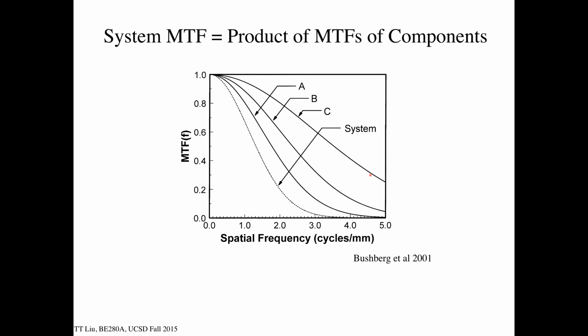Let's think about it a second. This system out here, system C, still has some amplitude for these high frequencies, right? And therefore, the point spread function in image space will be much smaller in diameter. The thing that I'm smoothing my image with will be a tighter, thinner function. This function, because I'm attenuating many high frequencies, they're gone here, will be a function that's broader. And when I do that convolution, it will blur the picture more. So more high spatial frequencies are missing, right?